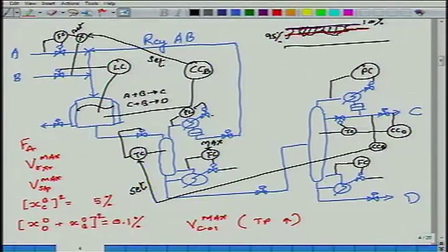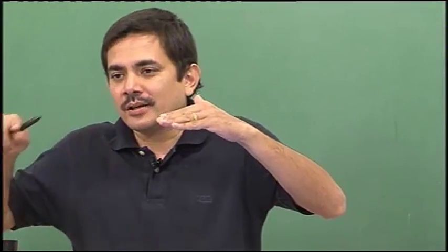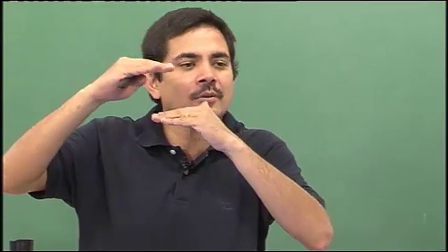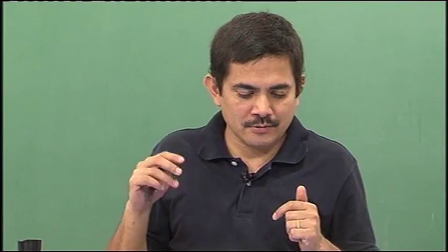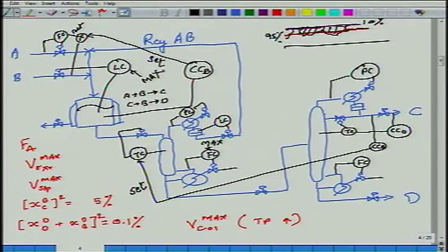Level control here is this way. Yeah, I have done CSTR level control, and I am going to say this guy is going to be almost max but not max. Why almost max? Because level is always the controlled variable. So level cannot be held really tight, it will show some variability. So you will have to back off a little bit no matter what, because it is a controlled variable, it is not a direct manipulated variable. Okay, so level is near max.